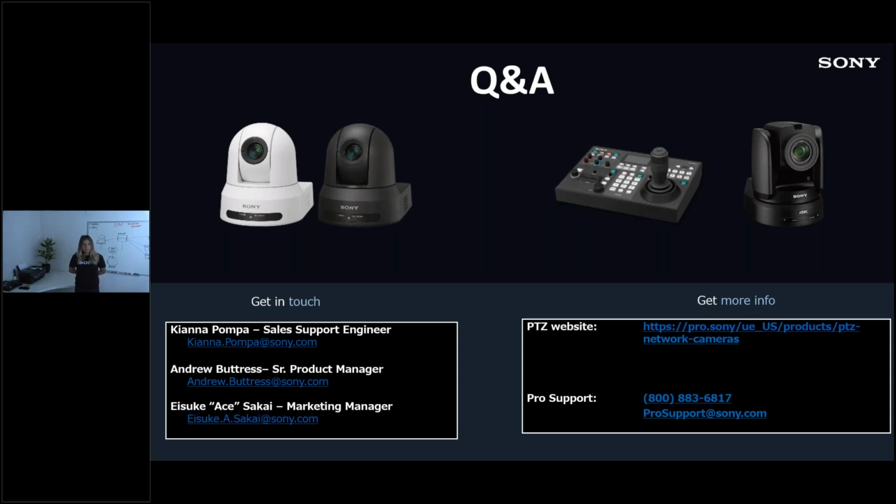Okay, thanks, Drew. Question from Colin. Can you control a camera remotely via RS-232? Our newer models are really VISCA over IP, and for serial VISCA, they're RS-422. The SRG-300H will do RS-232 control, and the SRG-120DH will also, well, actually any of the SRG-120D series, so we have the HDMI, SDI, and USB 3 versions, those will take RS-232. But to be clear, if you're thinking of Edge control with RS-232, the answer is no. It will only control HDMI output cameras that have VISCA over IP capability.